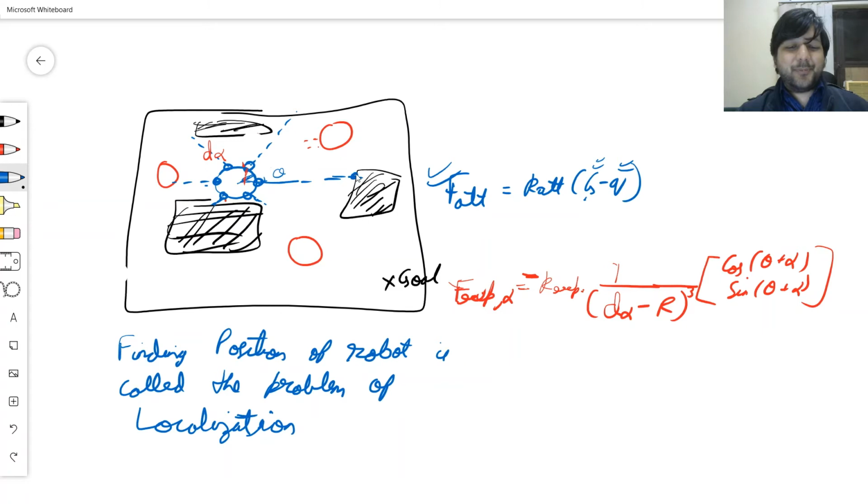So this reports one obstacle, this reports one obstacle, this reports one obstacle, and so on. You take all those obstacles and apply exactly the same formula. Every sonar in the sonar ring is at an angle. Sonar is poor man's LiDAR. So if you cannot afford the LiDAR, you take a sonar. Extremely bad sensor, but extremely low cost as well. Now here an interesting thing happens. So suppose, and this is what's called a black spot. So let me denote it by black.